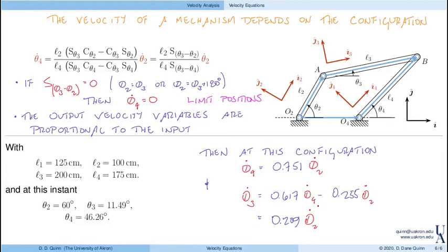So here we have determined how we identify the velocity equations for a mechanism. Essentially we take the loop closure equation that is valid for any time, and we evaluate how those individual terms change. Because it's valid for any time, the total change of the equation has to be consistent. And that then provides us with velocity equations. This should also give you a hint as to how we will ultimately get acceleration equations. We'll just take the derivative of velocity, which we've already learned how to do. It's just another vector equation, and we'll evaluate the change in that. But that's for another lecture.